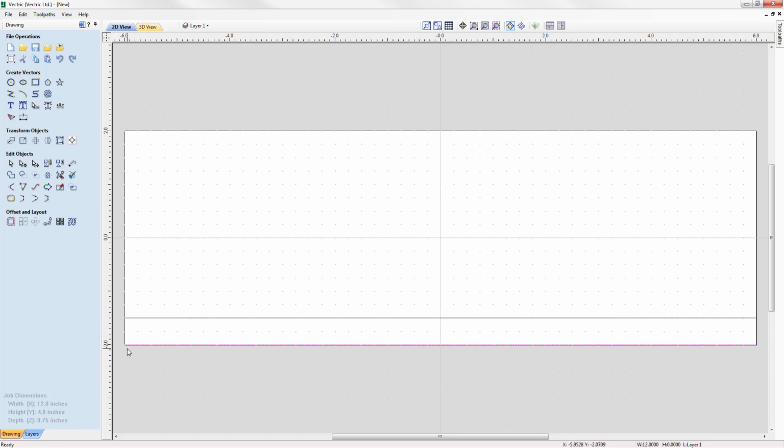I want to create another line that's going to go on the top of our job. So with that selected, again, hold down Control, left mouse click. I'm going to drag that to the top corner there. And then I want to create one more copy that is 3/4 of an inch down the y-axis. So I'm going to take that, hold down Control, drag that down 1/4, 1/2, 3/4 there. You can see that I can snap to position that in, and there I have 4 different lines, and they've all been accurately positioned thanks to the snap grid.